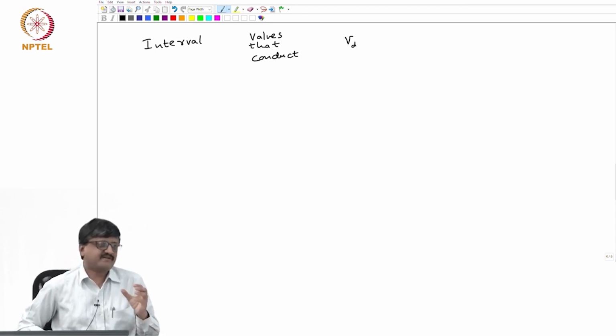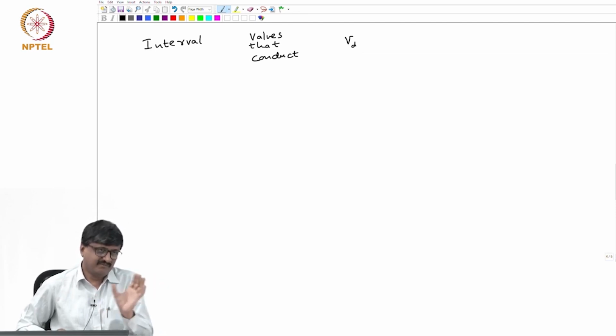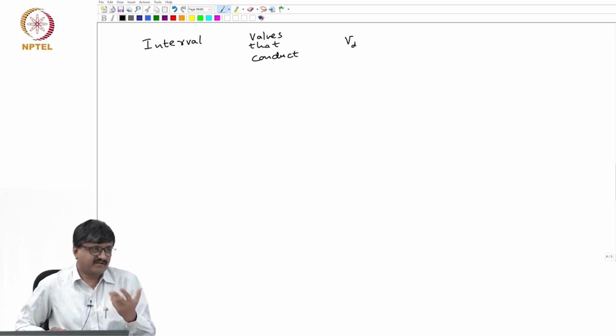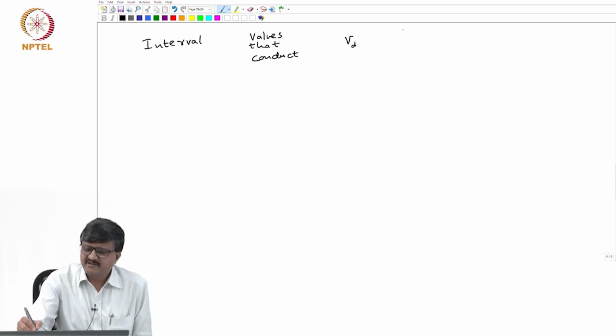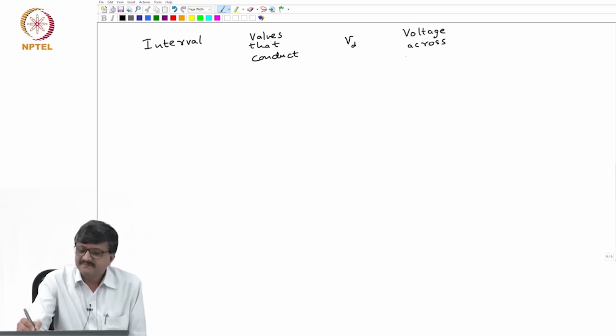The voltage across valve 2 will be identical to valve 1 except for a phase shift. So, the voltages across all the valves are identical except for phase shifts, and I can just see what is happening to the voltage across valve 1.